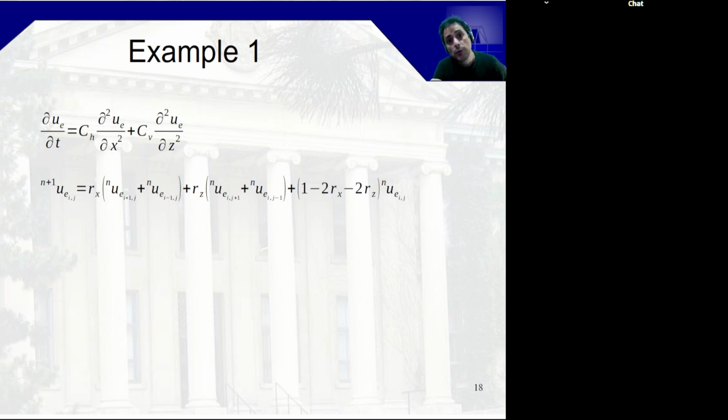For something like a circular footing or anything that is circular, symmetric in all directions, you can actually still use 2D, but you tweak it a little bit. So you're cheating basically. You're saying, well, it's the same way in all directions. Remember, that doesn't work if you have a specific condition on site where there's flow of water in a specific direction because of the local geometry. This works only if everything is symmetrical in all directions. Okay, and therefore you can do 2D to really represent a 3D scenario.